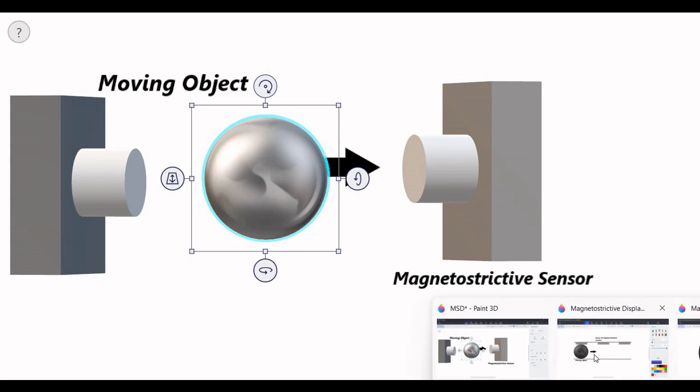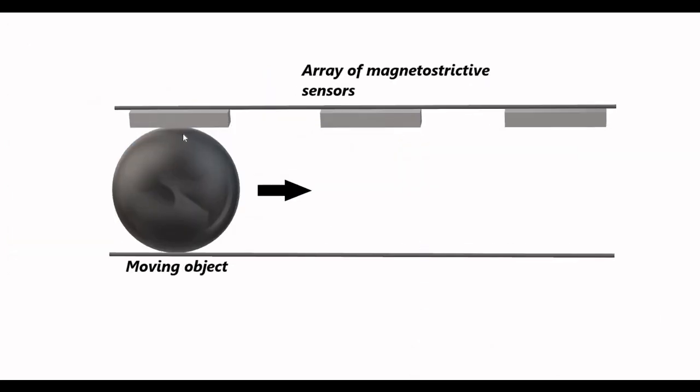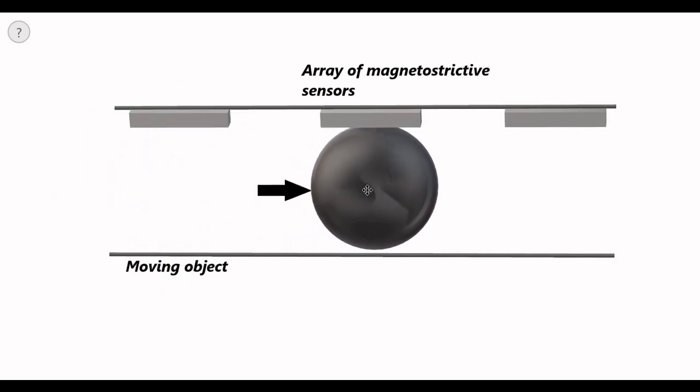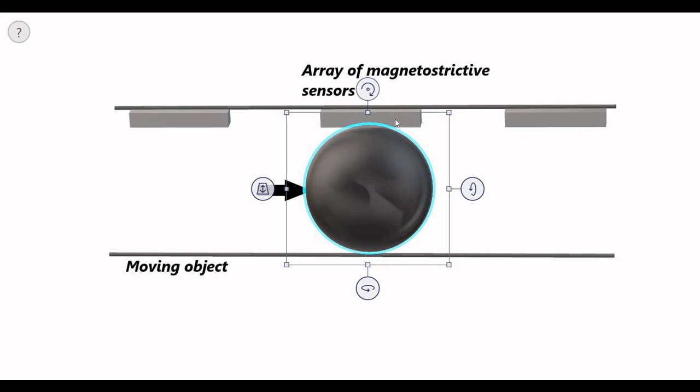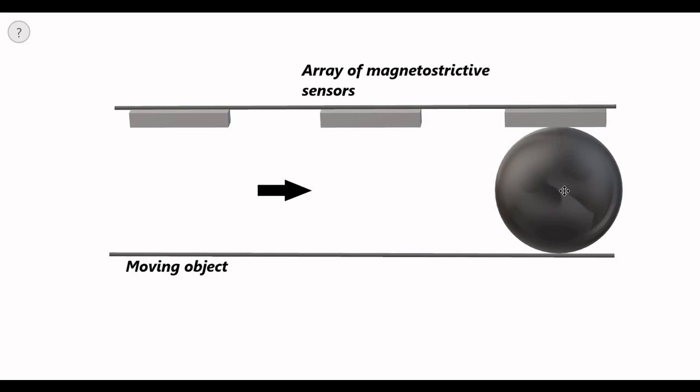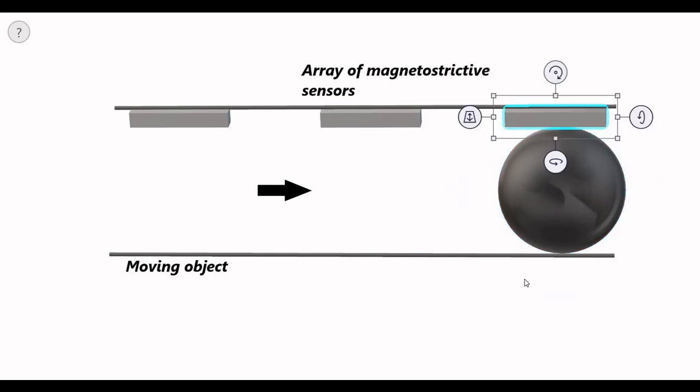The next arrangement is this, the linear motion arrangement. So here the object moves in a straight line path in a particular direction. As it is currently in this position, this sensor gets activated. As the object moves, it reaches this position again, this sensor gets activated, then it gets triggered and the signal is transmitted, and then as it finally reaches this position, this sensor gets activated. So here the sensors are placed at fixed distances. Separation distance between each sensor is same.